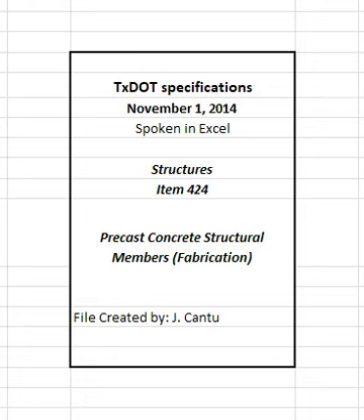Apply a form release agent, in accordance with the manufacturer's recommendations, to the facing of forms before placing concrete. Use a form release agent that facilitates form removal and does not affect any required coating, painting, or color staining operations. Do not use materials that appreciably stain or react with the concrete.